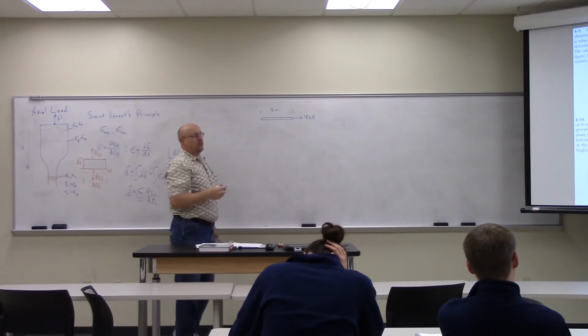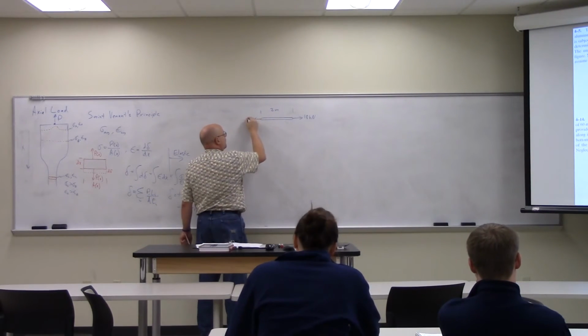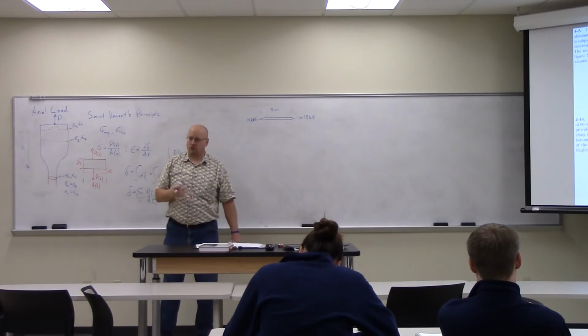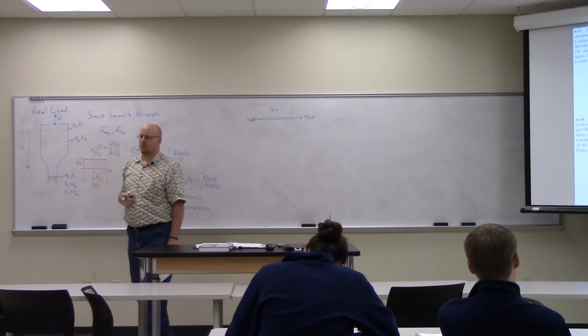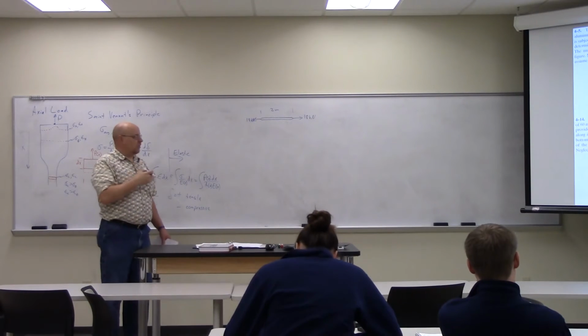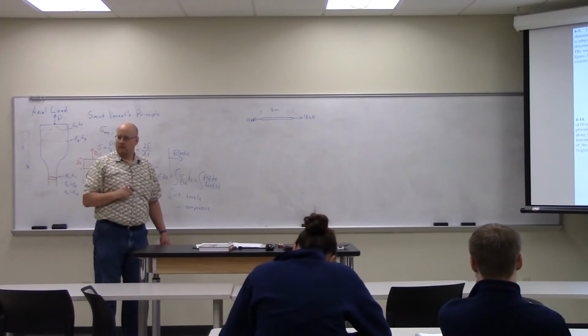So there's an internal force pulling in this direction of 18 kilonewtons, which means that member is just under tension. So I stop infinitesimally to the right of B, so that I get this nice simple system. Does that make sense? Yep.